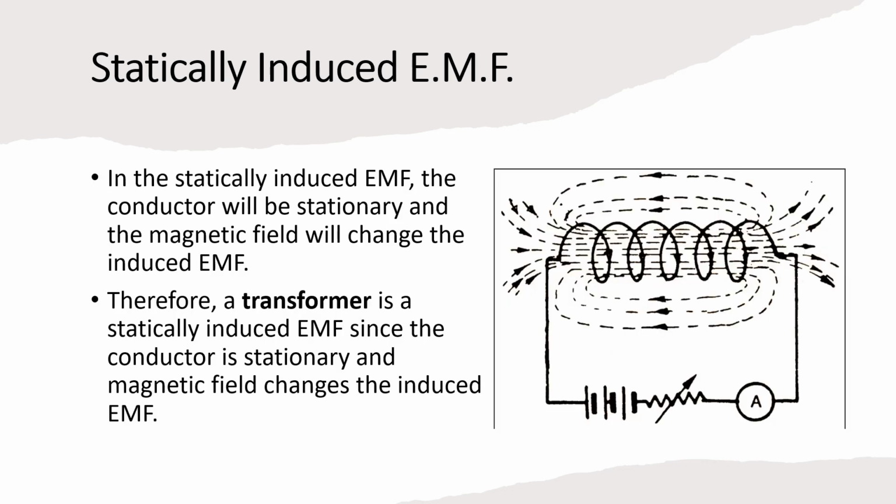In the statically induced E.M.F, the conductor will be stationary and the magnetic field will change, inducing the E.M.F. Therefore, a transformer is a statically induced E.M.F, since the conductor is stationary and the magnetic field changes the induced E.M.F.